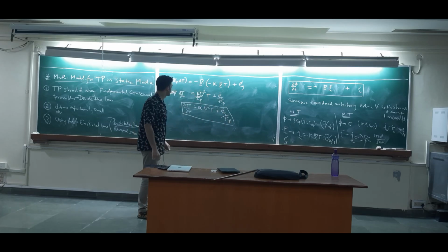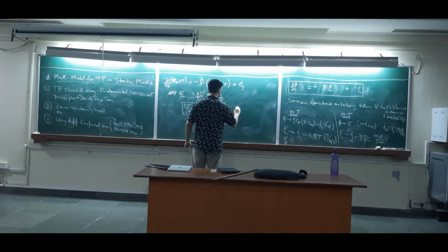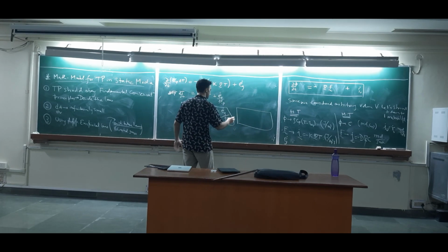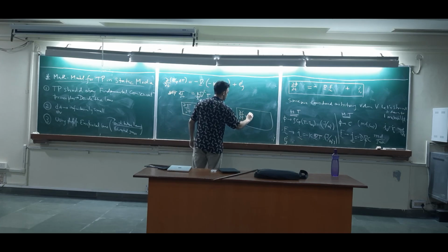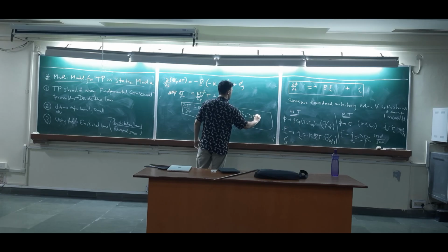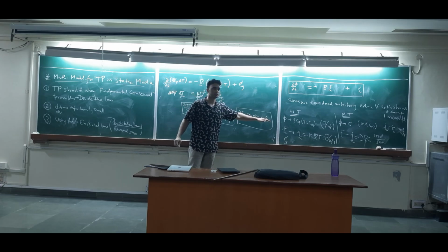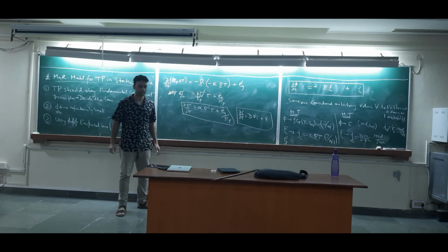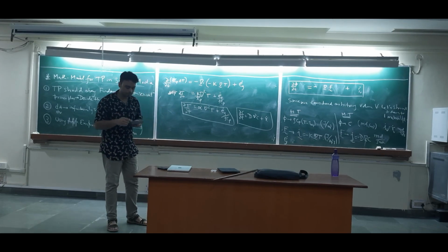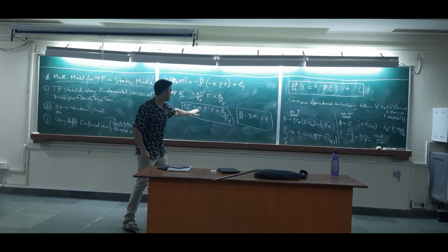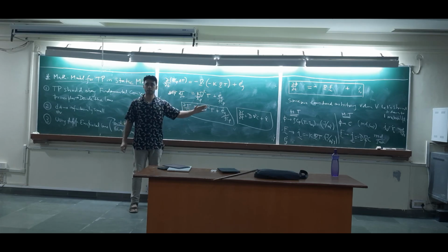You can do your mass diffusion equation. What you will get is, again, something for homework, very simple: dou C by dou t is equal to D del square C plus some volumetric reaction term, but not rho Cp. There are some differences. It's not the same. Alpha and D, now that you see both are analogous to each other, they should have the same units.